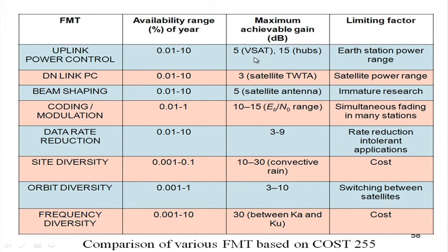Based on different sizing of the terminal you get different gains. For downlink power control, normally on satellites you get a 3 dB gain advantage. But the disadvantage is, as we have discussed earlier, that during normal operation, that is non-fade duration operation, you will be operating at a much lower backoff. So even with a 3 dB increase in EIRP, you do not enter into the nonlinear region.